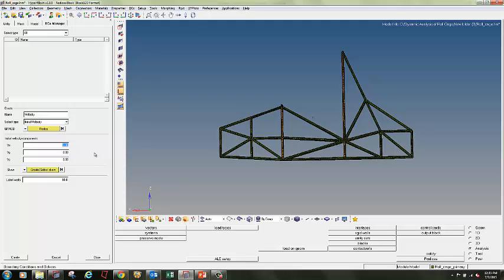Here we'll enter the velocity in millimeters per second, because all the parameters I am using are tons, millimeters, seconds and Newton. Let's assume I want to analyze this model at a speed of 60 km per hour.